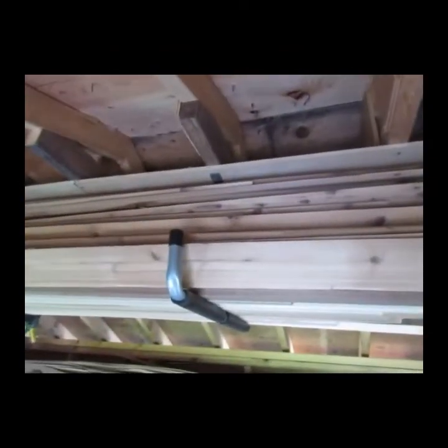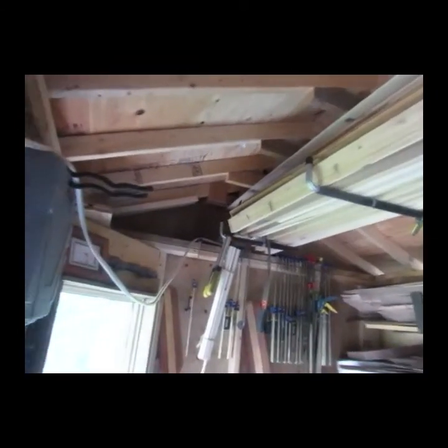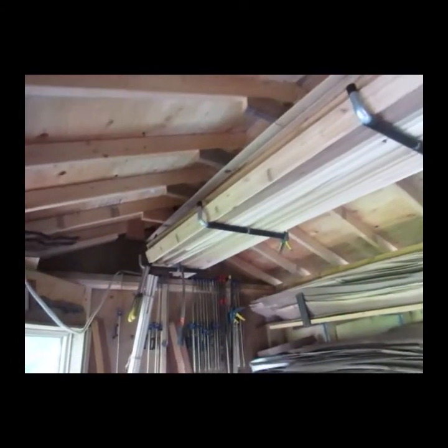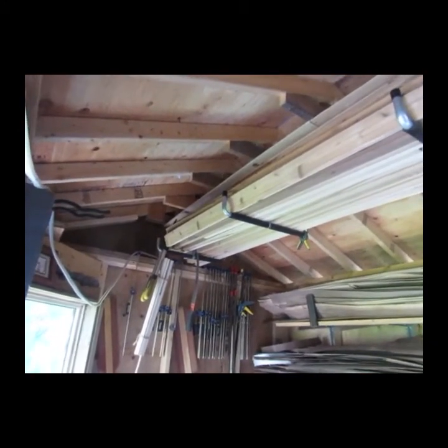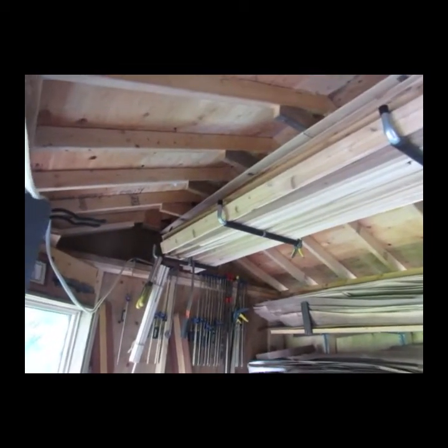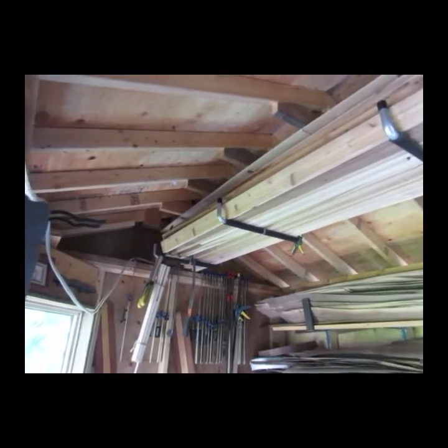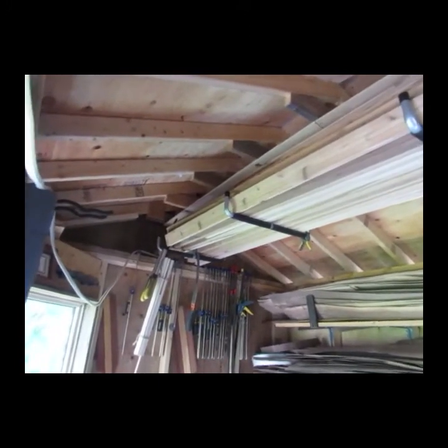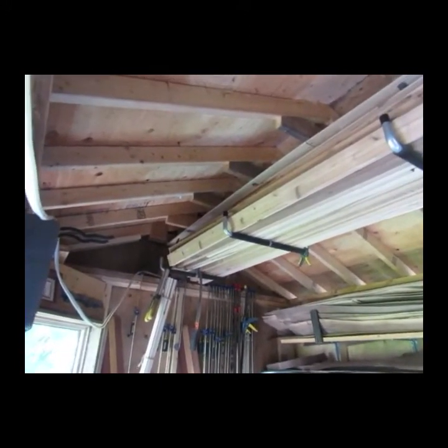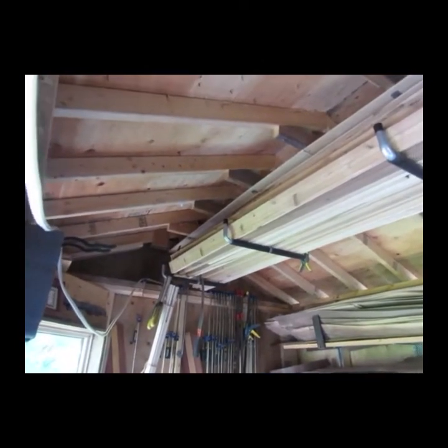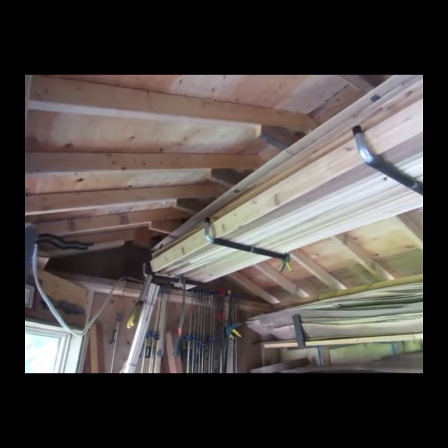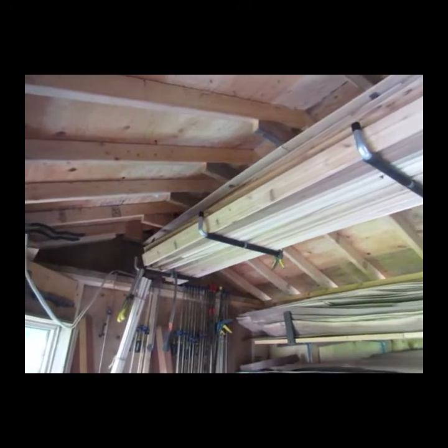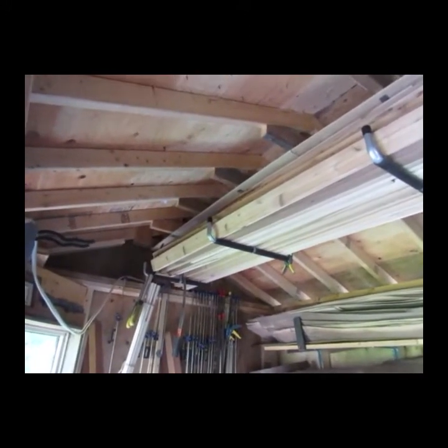So they put these ties in because they're afraid of updraft. When the wind starts kicking up in the real world, it can literally create a vacuum and pull up your roof. These ties hold the peak together. It's funny that that's a consideration that needs to be made, but it's very true. If you talk to your science teacher about the uplift of an airplane wing, you'll understand it a little bit more. But as wind blows across the roof, it creates a vacuum when it goes over the peak of the roof, and it literally has an uplifting quality or force. So those collar ties tie that together.